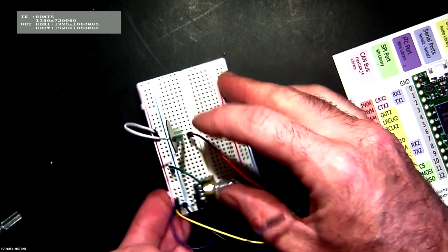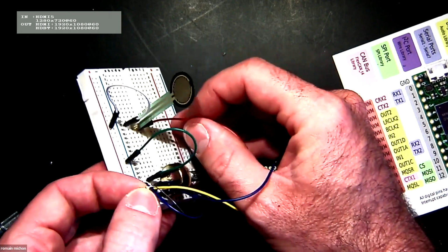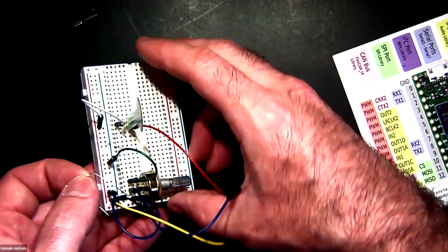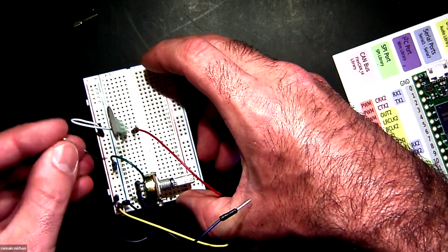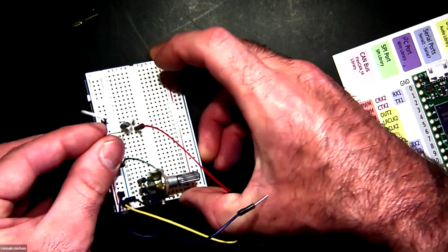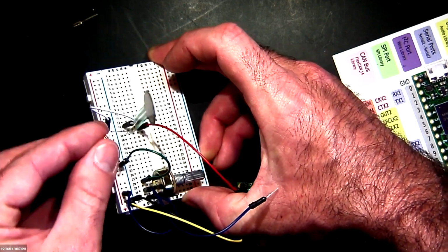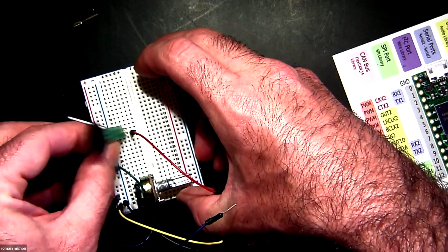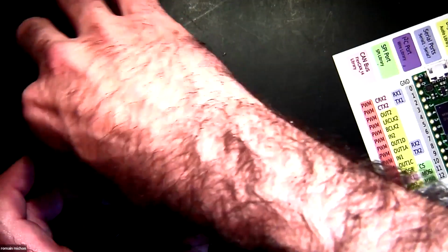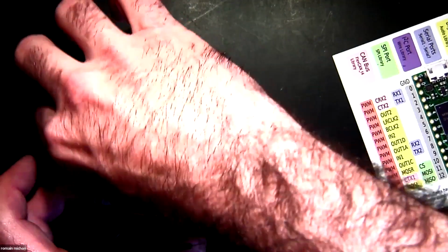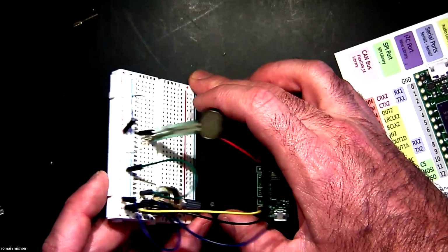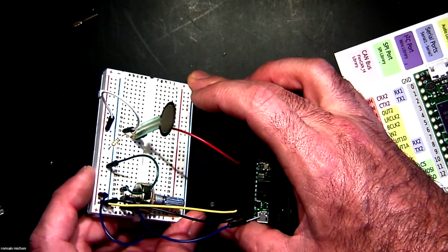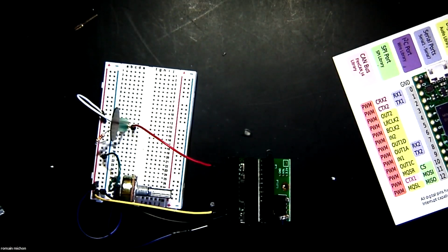The red wire that I have here is the wire that's reading the value from the FSR, okay? So what I'll do is that I'll just put a resistor here, okay? See? So you can actually put resistors directly on the breadboard, and then I will connect the other side of the resistor to the ground, just like that. Does that make sense?